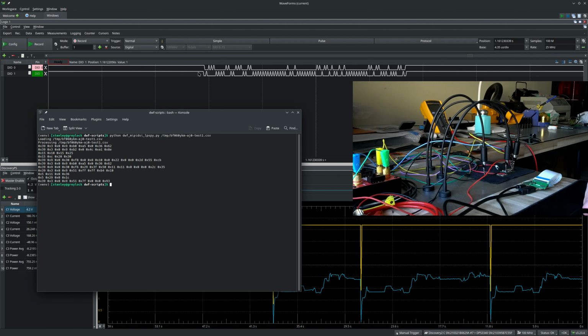So for instance, hex 39 is the DCS long write command. Hex 15 is DCS short write with 2 parameters. Hex 5 is this single parameter thing which is used for like setting the power modes.